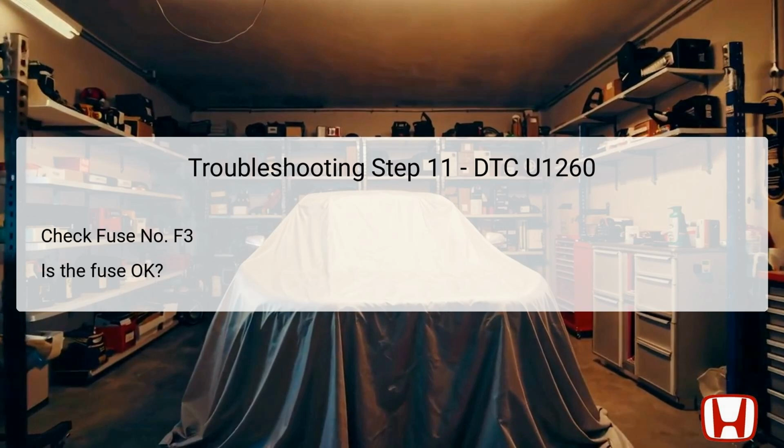If it's blown, the fuse should be replaced, and further checking is necessary to prevent recurrent issues. Should the replacement fuse blow again, it signals an underlying short in the circuit linked to this fuse, which requires an in-depth inspection and repair. Ensuring that all fuses are in excellent condition is essential for the vehicle's electrical systems to maintain optimal performance across all components.